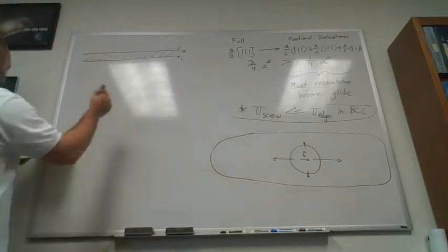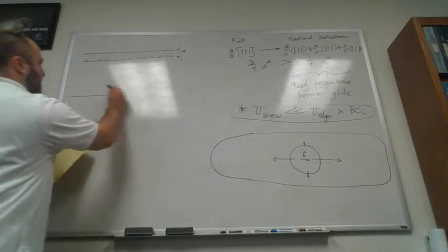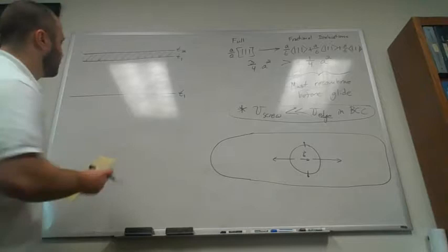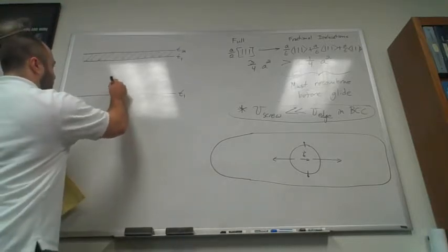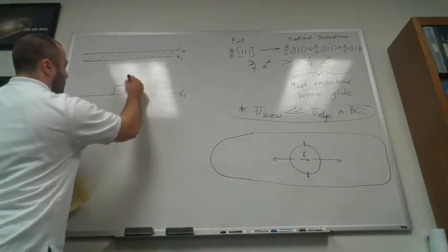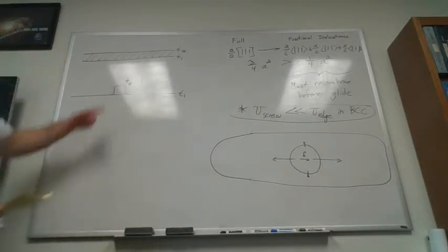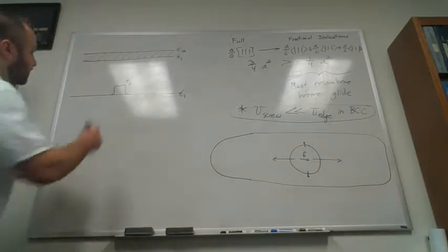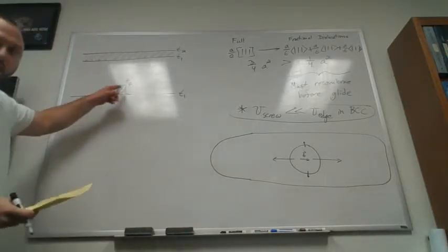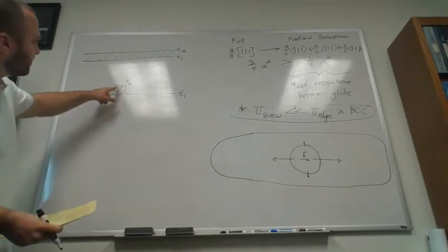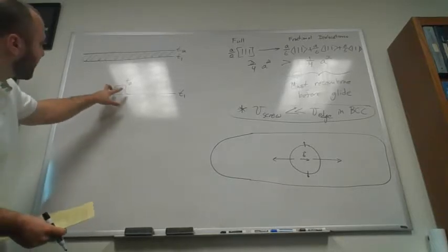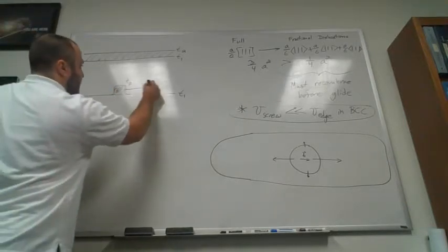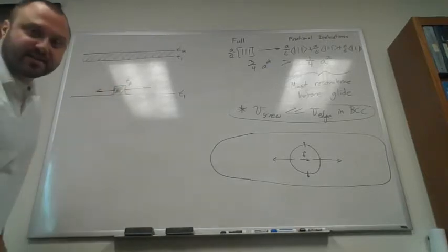Okay? So, alternatively, let's think about this dislocation at time 1. What if just one little local area changes? What if at time 2, we look largely the same, but just one little piece has recombined and moved? What would that look like? So there'd be an energy penalty, sure, but it's a relatively small one. But now what we have is that screw, which is slow, and these 2 new sides, which are edges. And those can move really fast. So these things can unzip really fast.